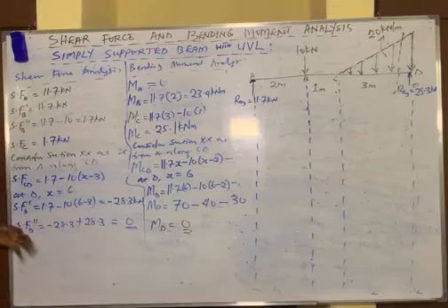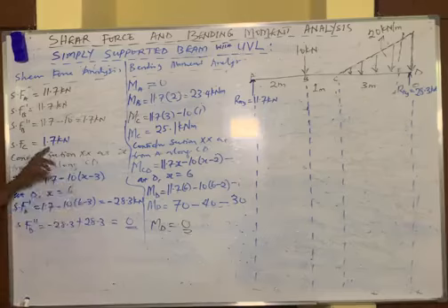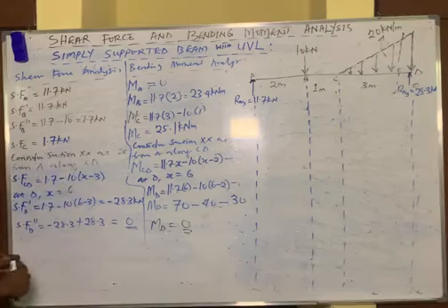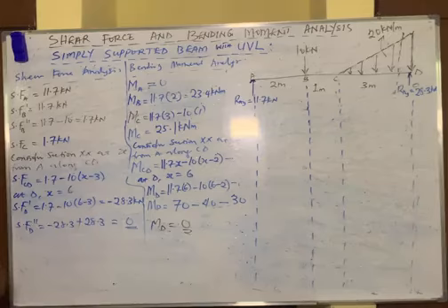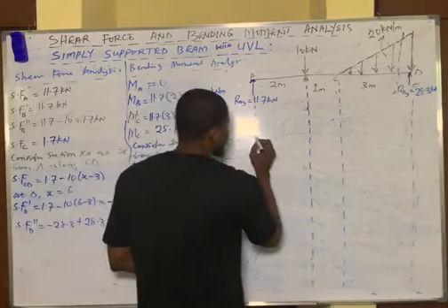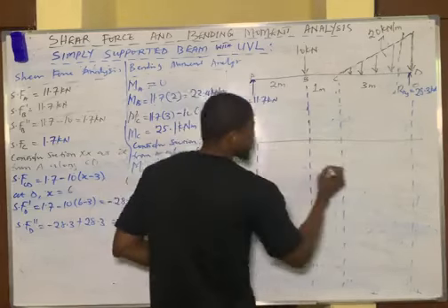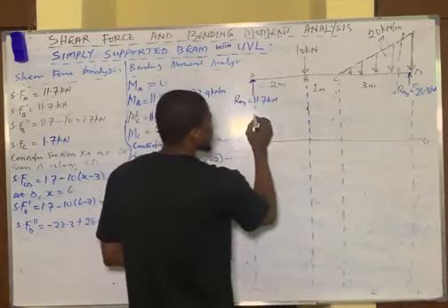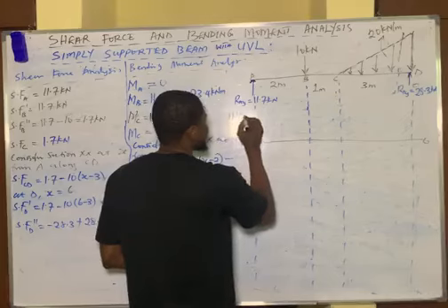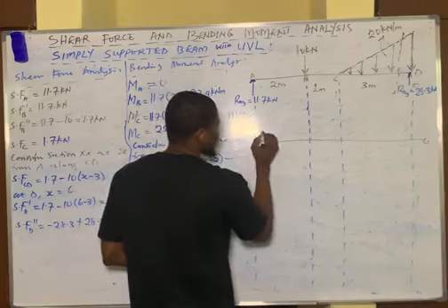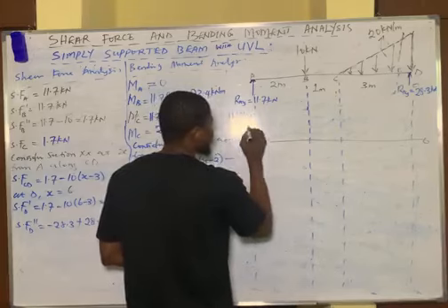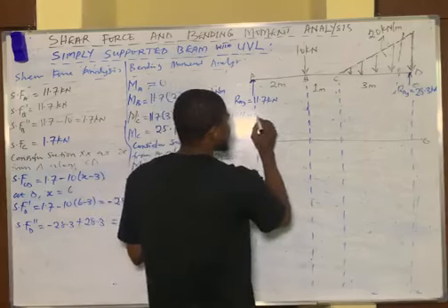Okay, from the shear force analysis, my lowest value is 0. Apart from 0, I have 1.7, and then my highest value seems to be 11.7. So approximately I have just three values, 11.7, 1.7, and 0. So 11.7 seems to be the highest. So you trace the origin. This is our origin, 0, 0. 11.7 kilonewtons can be kept here. Then you have 1.7 kilonewtons. You can keep that here.